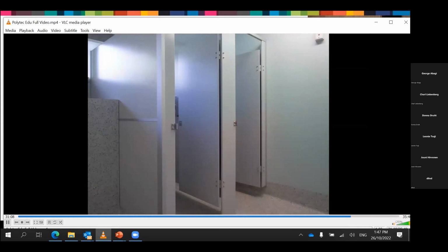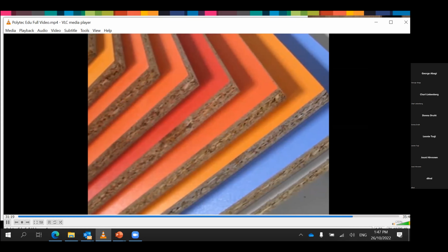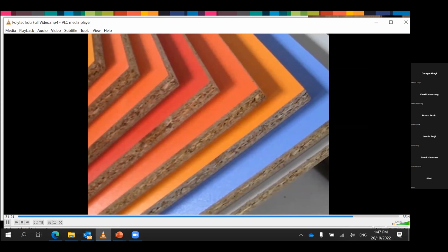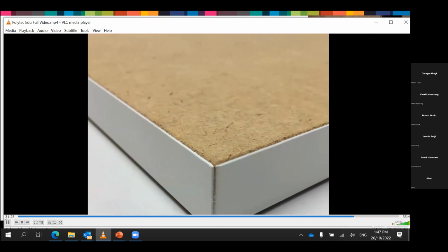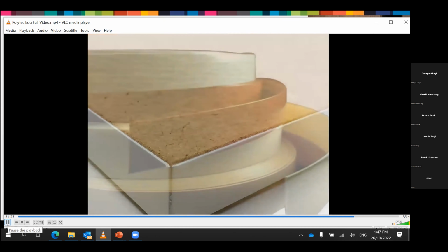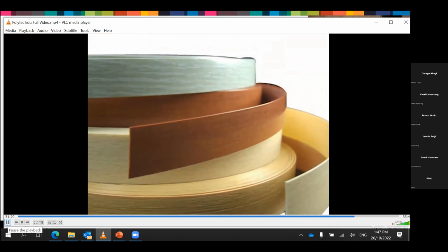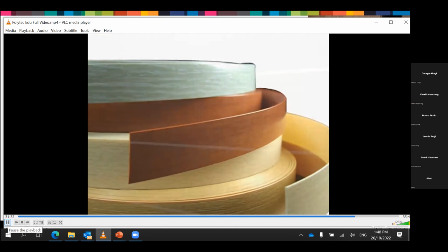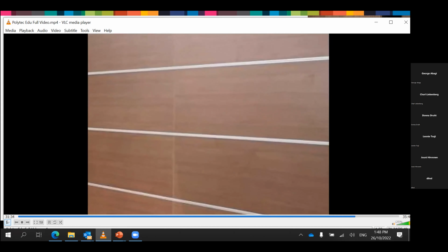When using compressed fibre cement sheet, keep in mind that a horizontal or H-profiled aluminium member is required in the middle of a partition division panel. For a budget-wise substrate, use melamine pre-finished MDF or HMR particle board 33mm or 18mm thick, edged with 2mm thick solid colour PVC.